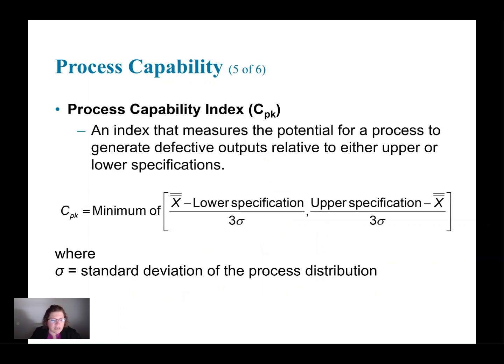So we can actually calculate the specific level of quality we are currently capable of using 2 major metrics. The first one is called a Process Capability Index, or CPK. That's a measure that basically measures the 2 halves of the normal distribution, the left-hand side and the right-hand side. And it measures both variability and centering. So CPK you can calculate as your overall process mean minus your lower engineering spec, divided by 3 times the standard deviation of your process.